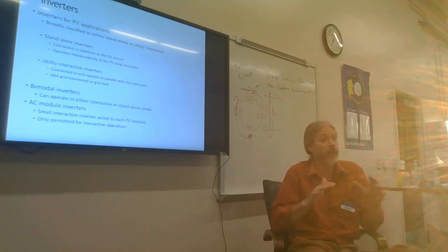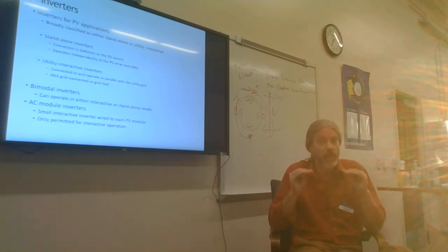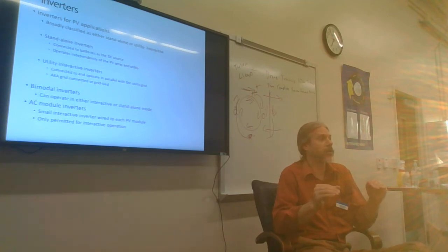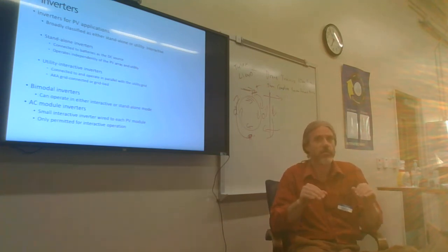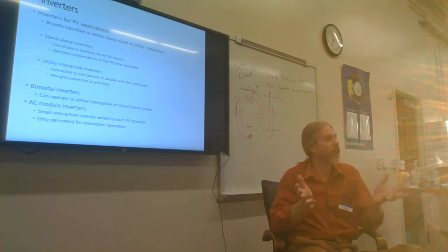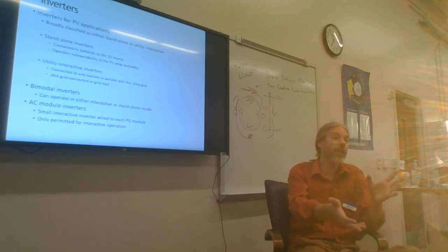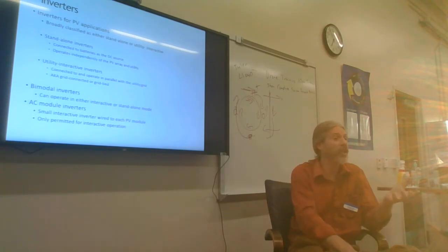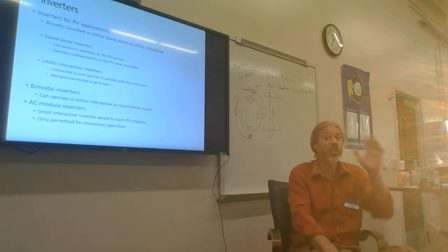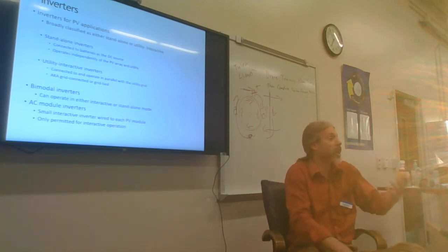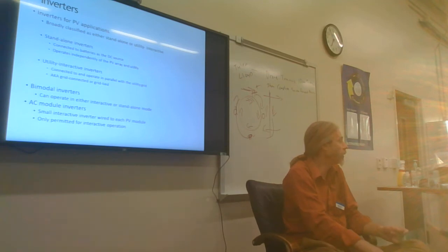And that's the reason that I will teach my students you only use microinverters to design for grid-tied, utility interactive systems. Period. Don't try to get fancy and say, hey, I'm going to use a few of these grid-tied inverters for an off-grid system during the day because it works all the time and it will help power these loads. Well, all it takes is one time for that to be shut down, and you're just wasting your power. There's nothing happening. All right.